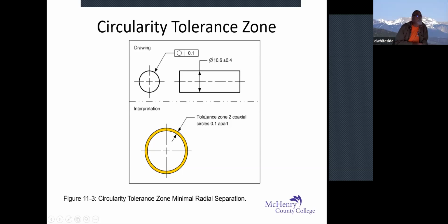But that would make something awful sloppy if it wasn't held, because if you're making something to fit something and it's got a tolerance, I was watching a video today where this guy shows this part and it has a tolerance of ±4, and the dowel he was using is going in the hole and it's got a ±4. By the time it's over with, it could be extremely sloppy if you don't hold the tolerance closer, right?